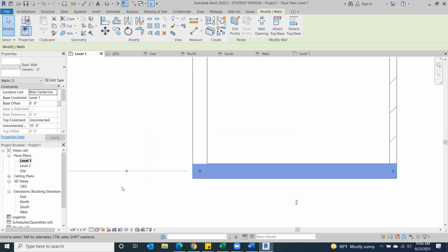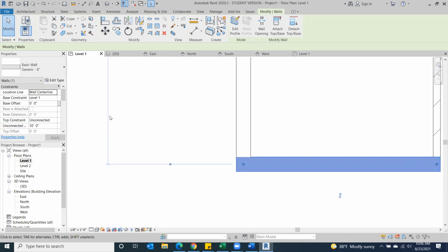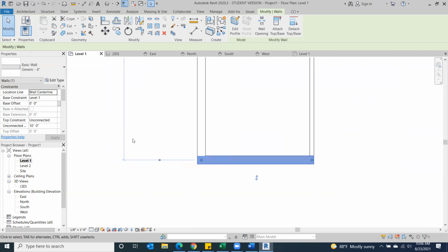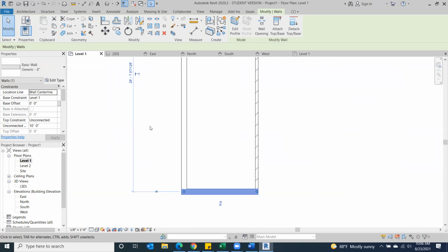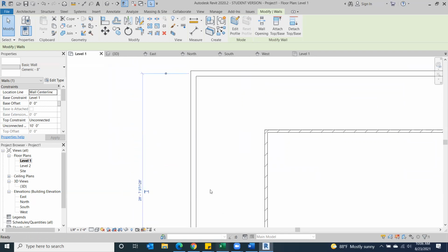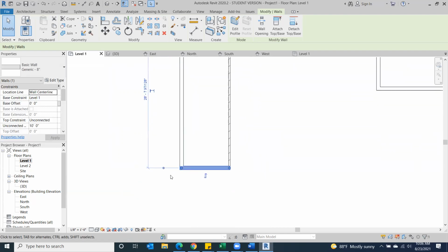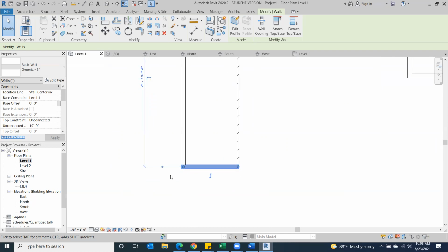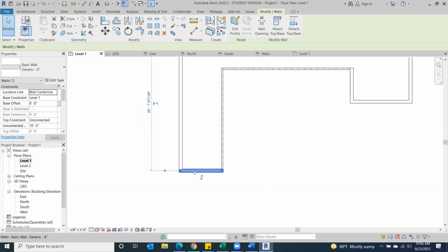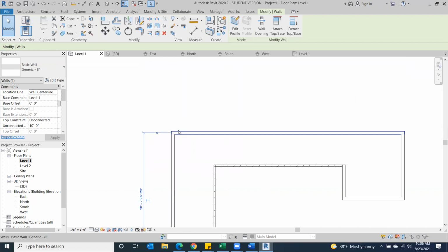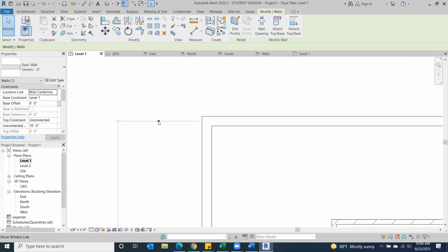Notice another thing, this temporary dimension line, and it's temporary because we're going to make it go away. These are not our final dimensions, what we look like when we actually start completing a sheet. But we do need them to set our parameters and our measurements. So this wall measured from center wall to center wall, center line, is 28 feet and all sorts of numbers. So that's not going to be super accurate for set plans. So we want to make sure that our dimension lines start and end where we're actually measuring from. So for our external dimensions, we want to go from the external line to the external wall line. So in order to do that with this node right here, I'm going to click on it.